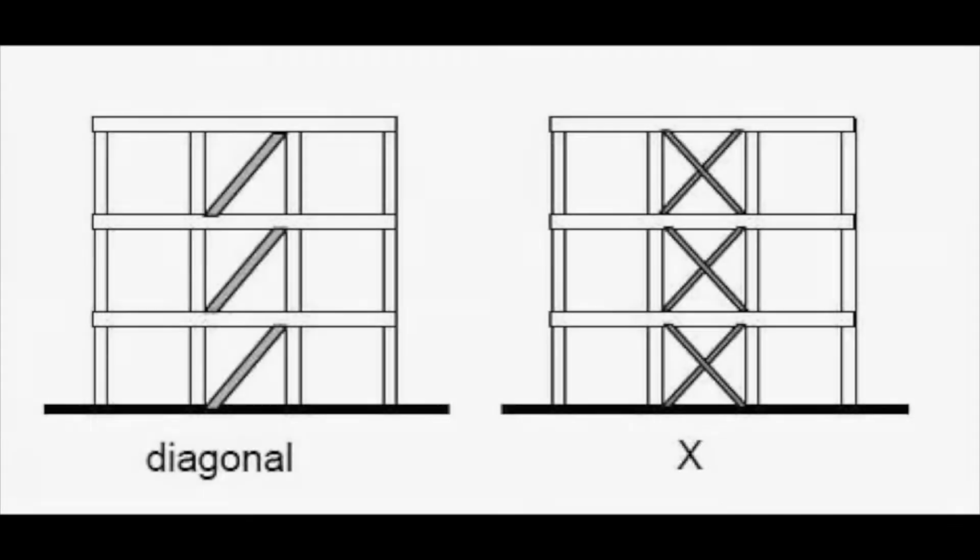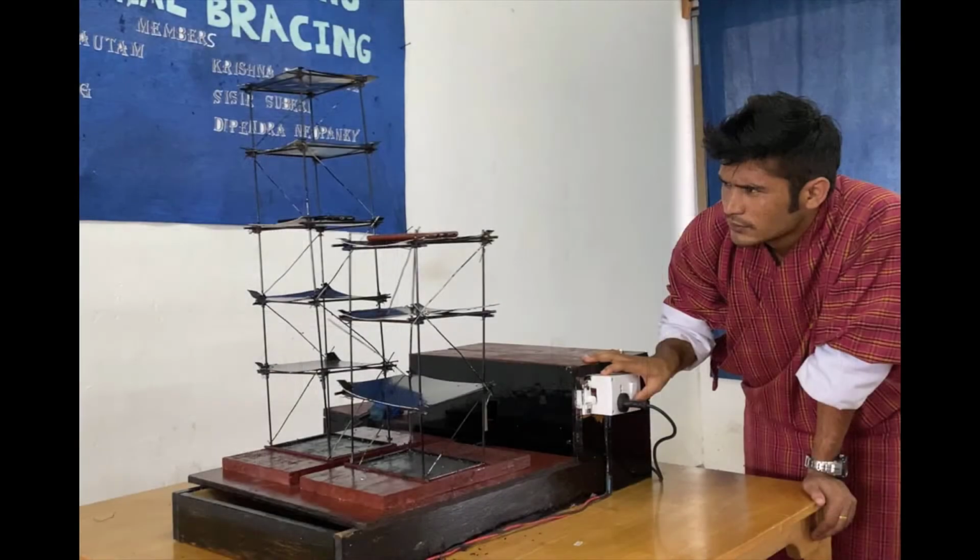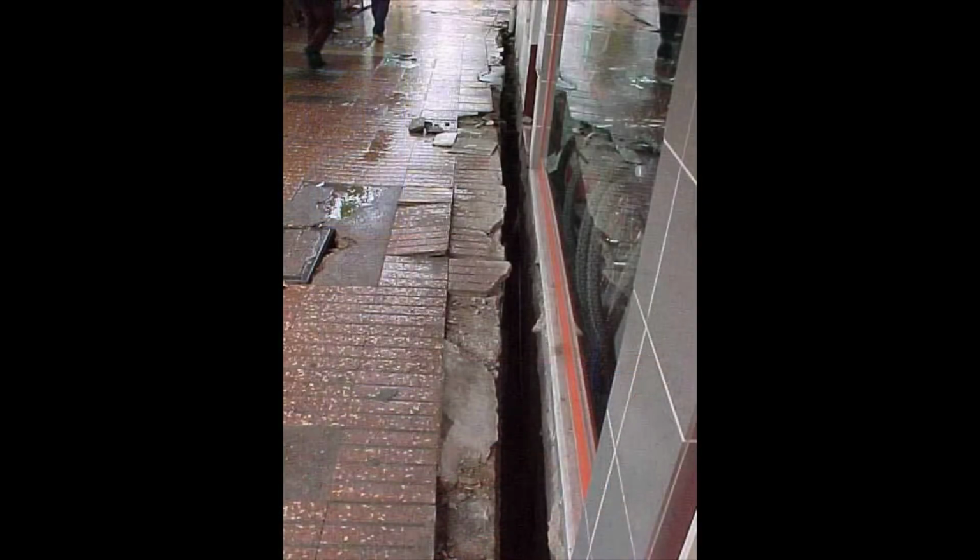For the next case, we will be looking at the addition of diagonal braces to minimize the lateral displacement of the structure. Diagonal braces act as lateral force resisting systems in high-rise buildings by withstanding the tension forces. As we had seen in the earlier demonstrations, the tall structure has noticeable lateral displacement. Let us see how this can be fixed by adding diagonal braces to the structure.